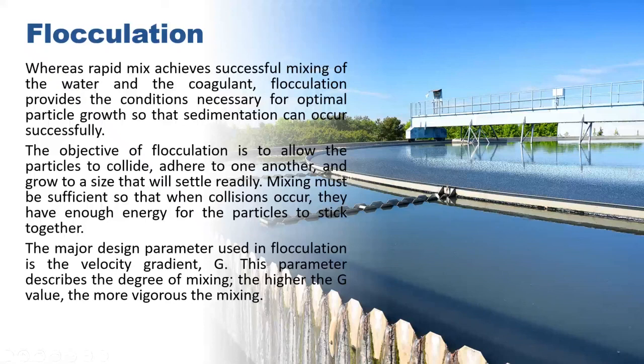Hi everyone. For the continuation of the water treatment and technology, now we will discuss flocculation. Whereas rapid mix achieves successful mixing of the water and the coagulant, flocculation provides the conditions necessary for optimal particle growth so that sedimentation can occur successfully.